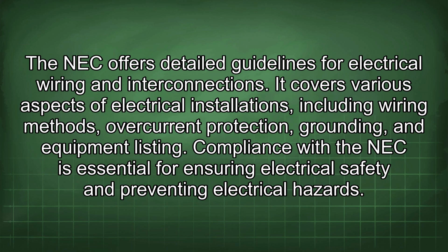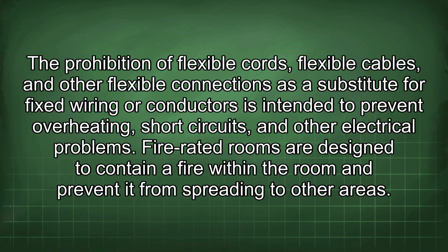The NEC offers detailed guidelines for electrical wiring and interconnections. It covers various aspects of electrical installations, including wiring methods, overcurrent protection, grounding, and equipment listing. Compliance with the NEC is essential for ensuring electrical safety and preventing electrical hazards. The prohibition of flexible cords, flexible cables, and other flexible connections as a substitute for fixed wiring or conductors is intended to prevent overheating, short circuits, and other electrical problems.